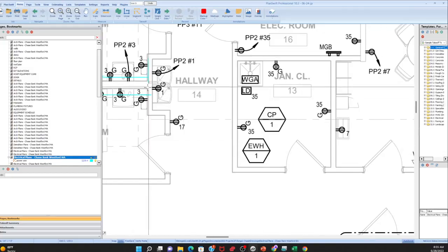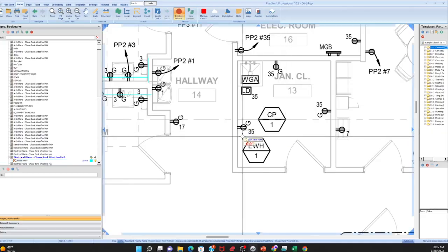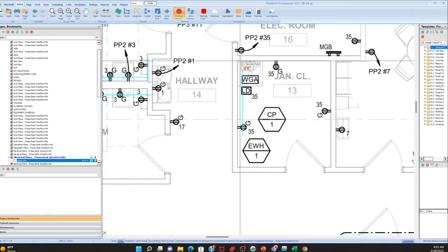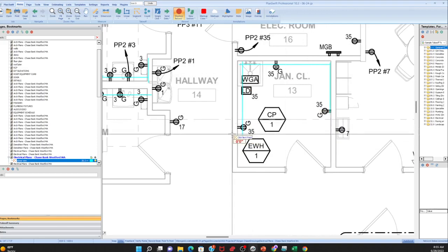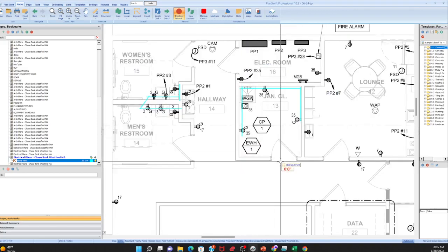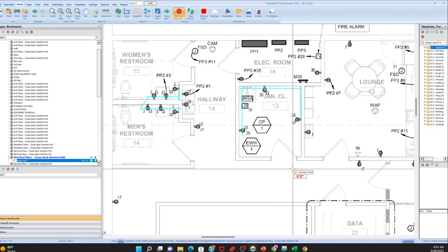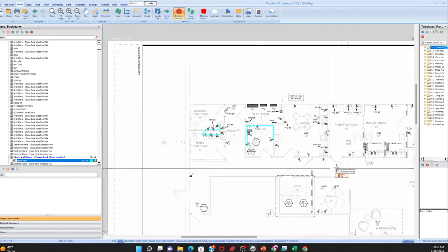So you don't have to worry about, oh, should I go from here to there? What you want to do is just remember all these are 35, so I know I can use MC cable. And I'm just gonna do that because even if my electrician is sloppy, I've covered all of that. I'm going to do it in the neatest way possible, that way I'm not going to be short. And again, on the wire and conduit runs, you're not trying to be exact. You're trying to get an amount that's comparable that will cover the job. And if you go from point to point, add 10%.